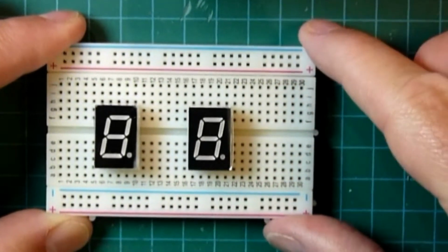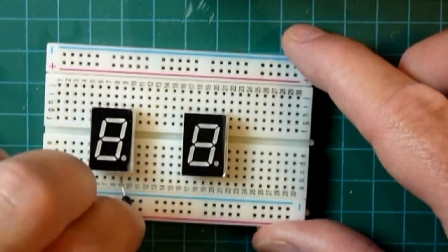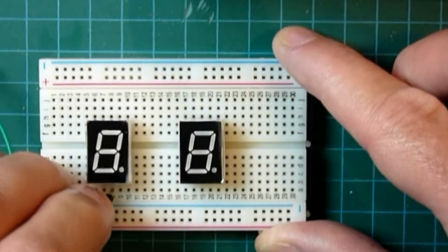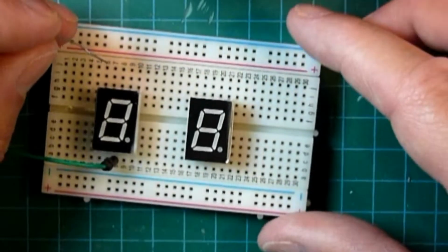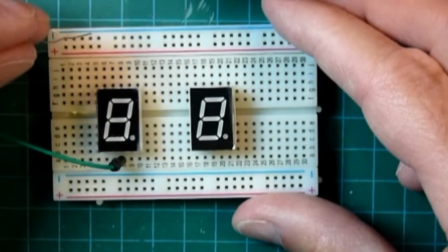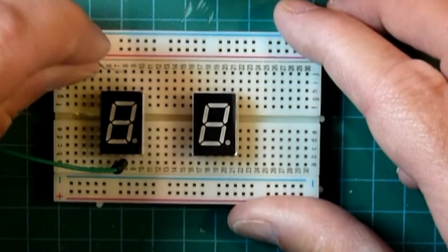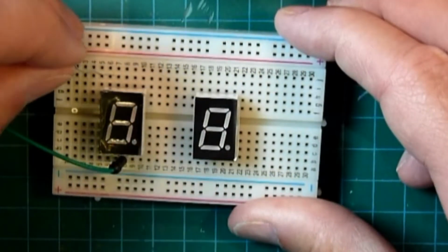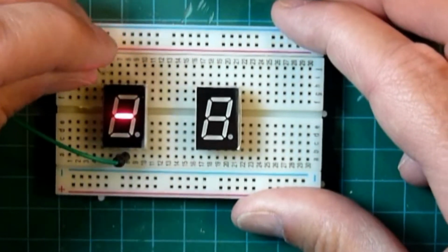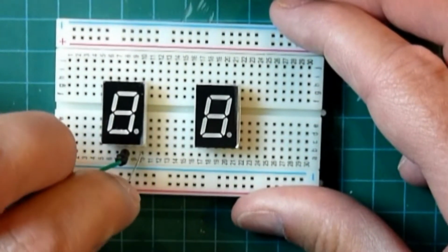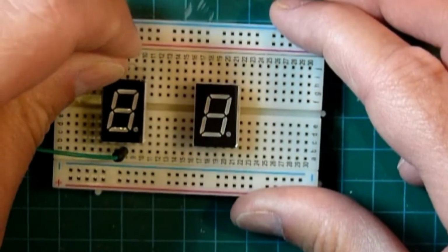Now let's connect this to a 5-volt supply. I have it preset here. I'm just going to plug it in, and you'll be able to see the segments light up. We're also going to measure the voltage drop across this device so we can calculate what resistor value we should have. I'll show you that shortly. Here I'm plugging in across one of the segments, and there you see the center segment light up. I'll light up the decimal point here. There it is. And as you go around you can see each segment lighting up.